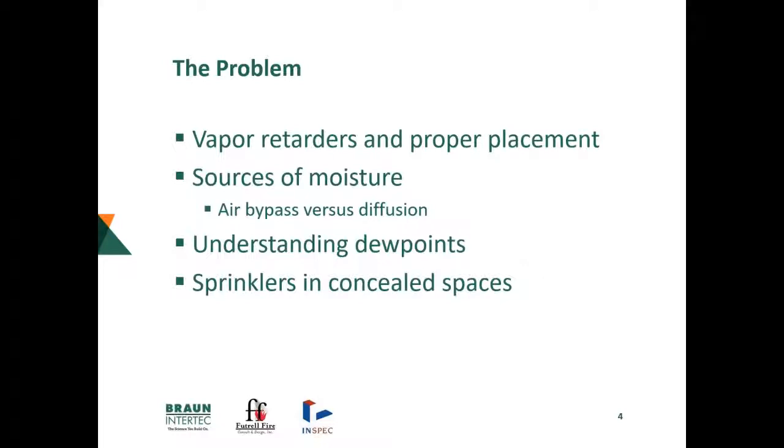And in this community where we have a lot of these buildings being built with this type of detail, we anticipate seeing more of the growth in these problems. So there's also an understanding of the sprinklers and the concealed spaces and what will and will not work. We see with all the insulation going in that you can create an area where the heat won't get to the sprinklers and can cause some frost and breaking of pipes.